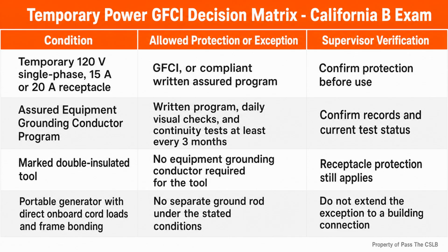Imagine a remodel where someone proposes attaching the grounding connection to a convenient metal sink pipe on an upper floor. The pipe may look continuous today, but the location is beyond the allowed first 5 feet from the point of entrance. I would reject that shortcut and coordinate the connection at the compliant location through the electrical contractor.